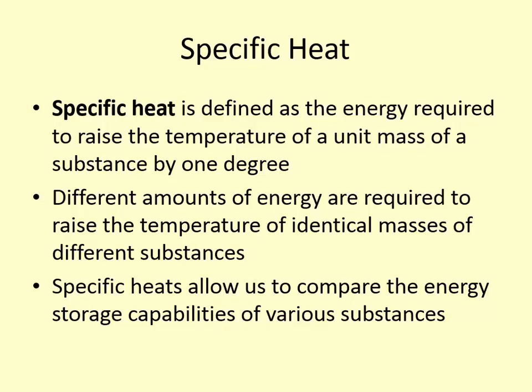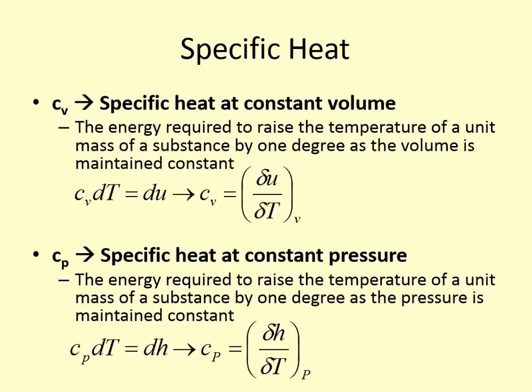So specific heats will allow us to compare energy storage capabilities of different materials, and it can be beneficial to us in many ways. One, if we are looking for a material that removes heat very readily from another substance by thermal contact, then we would want something that has a very large specific heat, meaning that it can remove a lot of energy for changing that temperature.